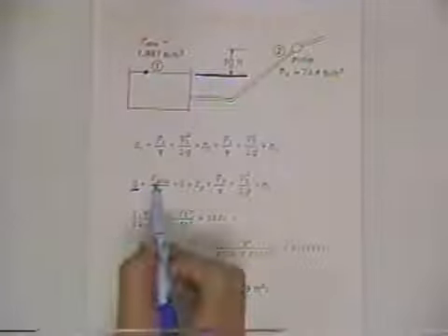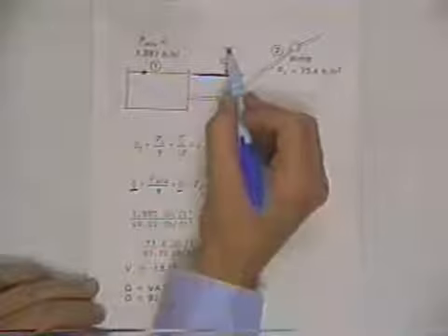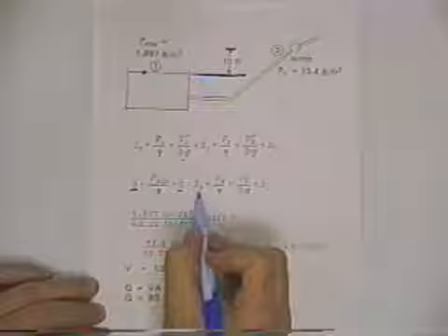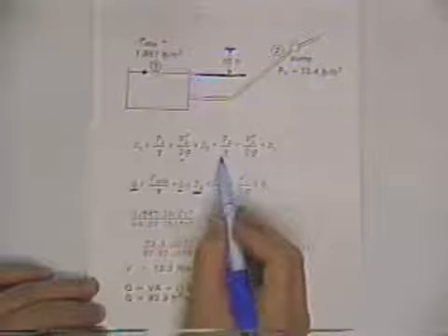but we're going to use absolute pressure now, and we're going to set the pressure at atmospheric pressure. And of course, atmospheric pressure divided by the unit weight of water gives you the pressure head. We'll let the velocity be 0 again, and so the velocity head is 0. Now, just generically, we could call that the head at which the pump is vertically located above the sump, Z sub P, and we're going to set this pressure equal to the vapor pressure.